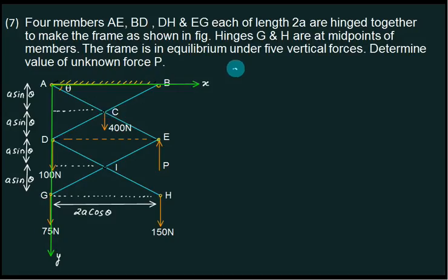So at point C we have P1 equal to 400. 400 is shown downward. So I require the y coordinate at point C. If downward or upward, you require the y coordinate. If horizontal, leftward, we require the x coordinate. So what is the y coordinate of this point from the origin A? Is it A sin theta? Fourth quadrant, our direction is downward. What is the derivative of YC? It is A cos theta del theta.